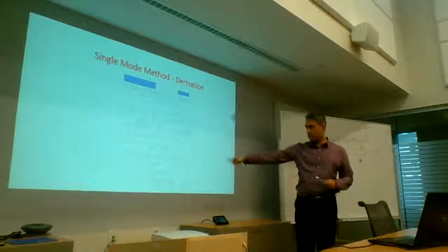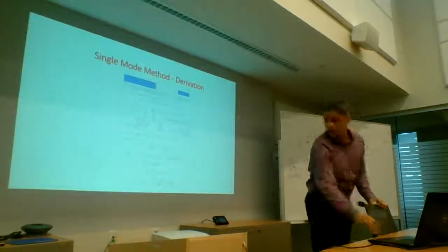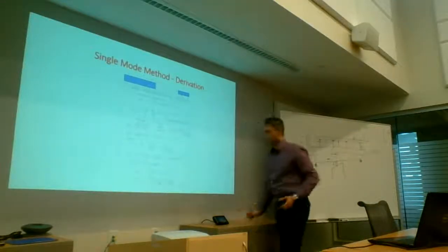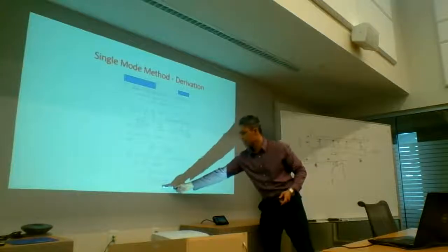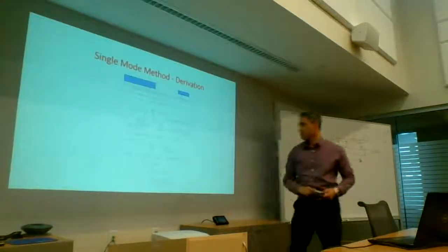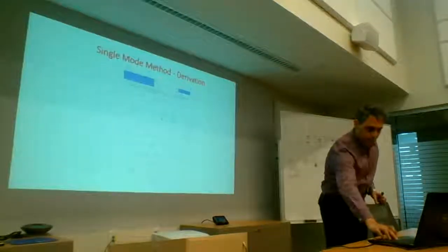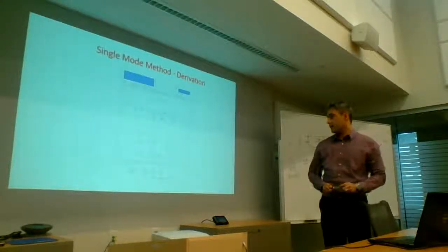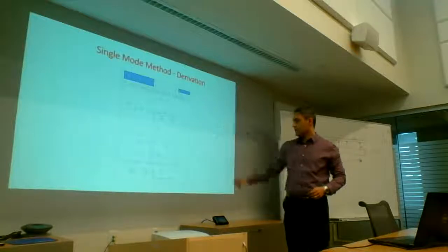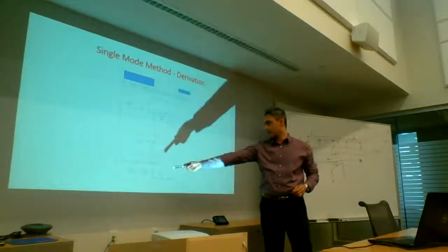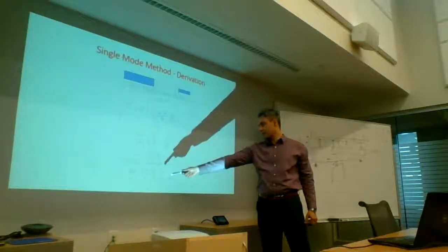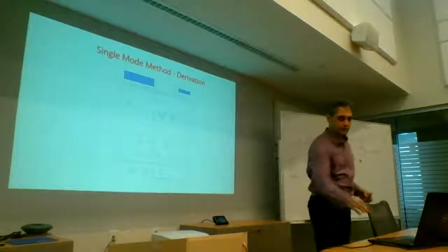And once you go through that, you exactly arrive at what the code is doing. So if you look at some of these, you'll see I've put some physical meanings, like here's your mass and here is your mode shape. I'm not going to go too much into this except for the fact that when you combine all of this, you come up with your Vx, which is your spectral acceleration divided by your frequency squared times the mode shape times these two factors.